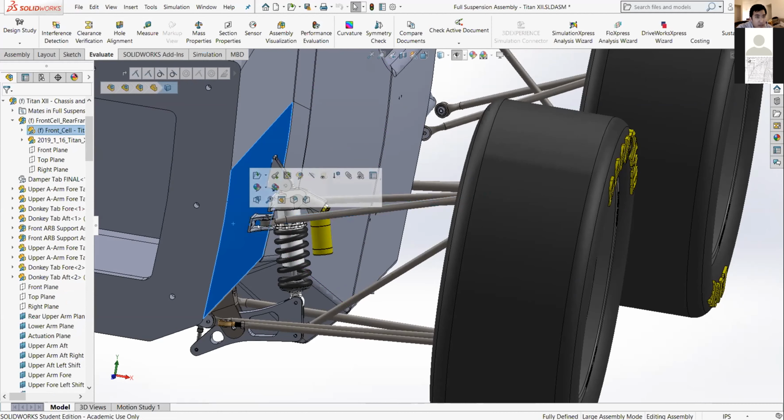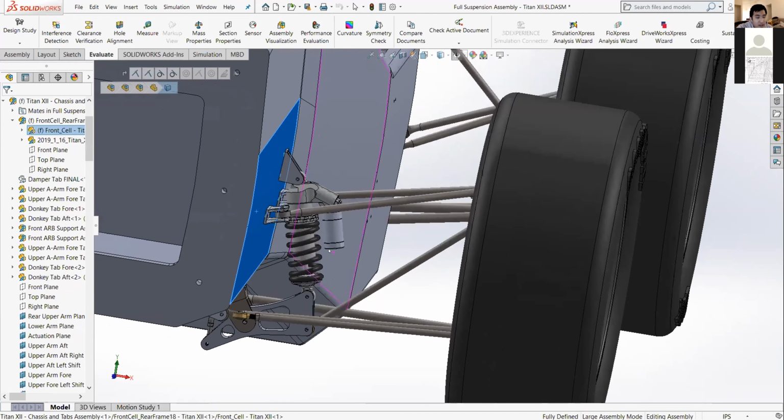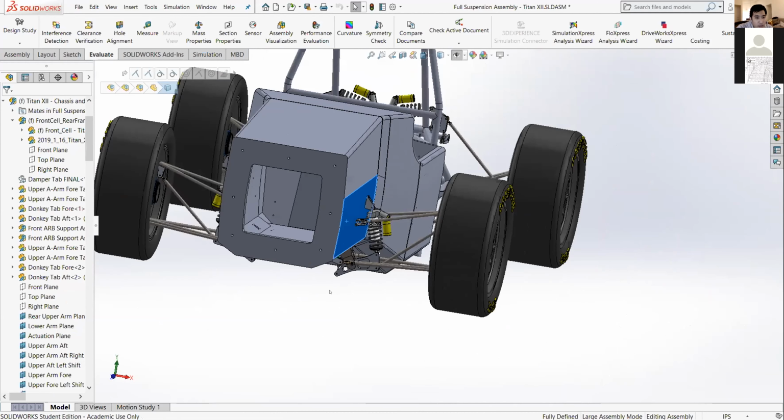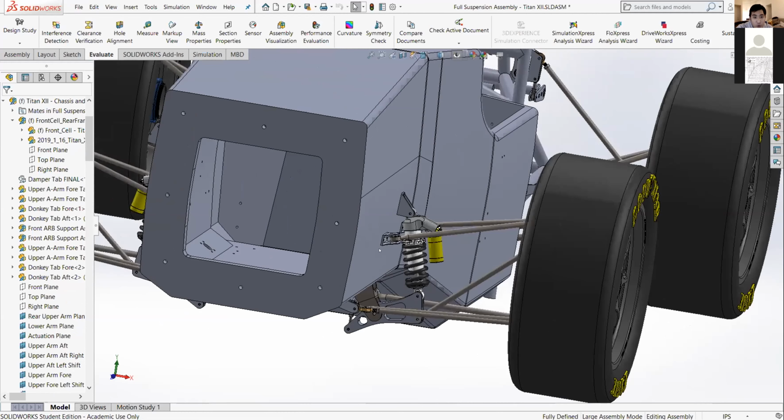If you do want to model those rods as beam elements and apply the loads there, that would be more accurate. And actually, you can do a comparison. You can compare the situation you talked about before, where you apply the loads directly on those holes, with the results when you do it with the beams, and see how that affects the results. I think that would be something interesting to do too.